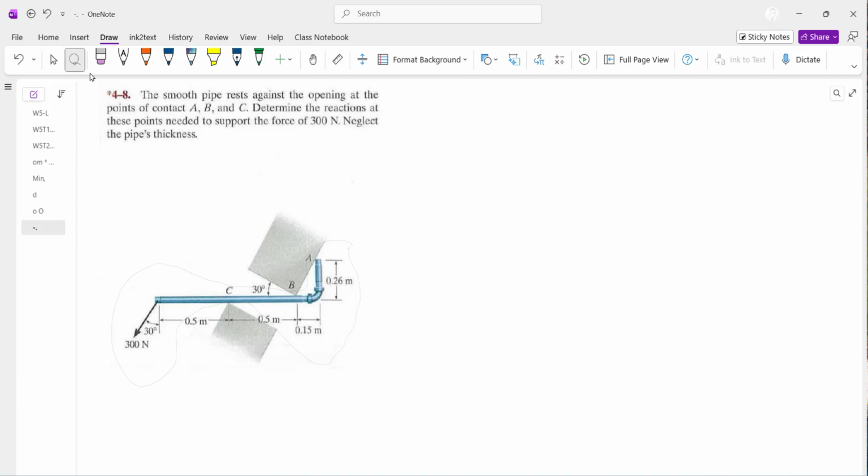But when you free them, those contacts should be replaced by external forces, because before freeing them at A, B, C you did have internal forces, action and reaction. Now you isolate this, you only keep one of the pairs, either the action or reaction. In this case we expose them and pretend these are external forces to make the free body diagram comparable to the non-free version.